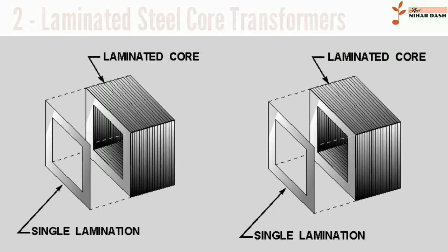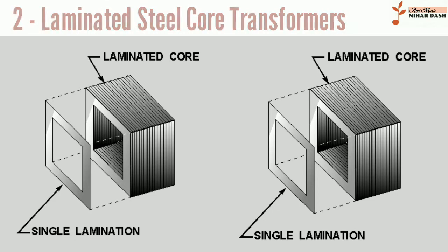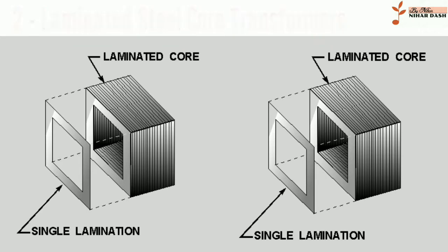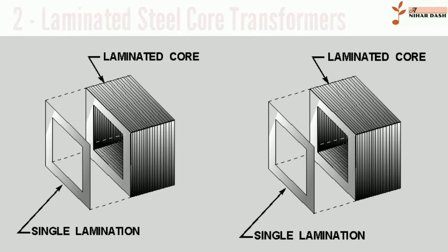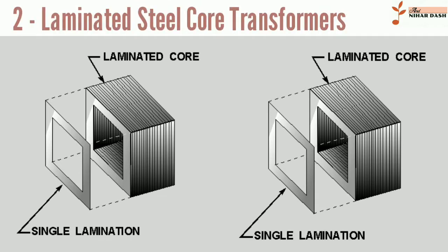Laminated steel cores. Laminated core transformer showing edge of laminations at top of photo. Interleaved DI transformer. Laminations showing air gap and flux paths. Transformers for use at power or audio frequencies typically have cores made of high permeability silicon steel. The steel has a permeability many times that of free space in the core, thus serves to greatly reduce the magnetizing current and confine the flux to a path which closely couples the windings.